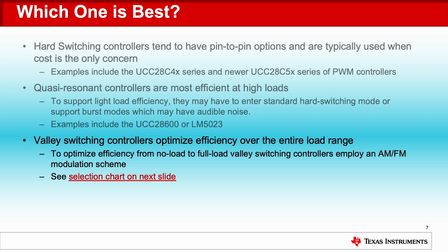Valley switching controllers optimize efficiency over the entire load range. To optimize efficiency from no load to full load, valley switching controllers employ an AM/FM modulation scheme. You can see the selection table on the next slide.